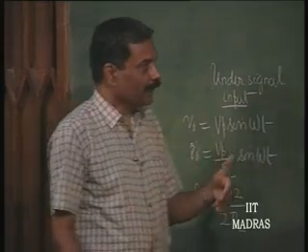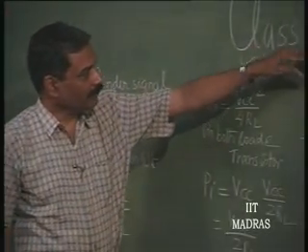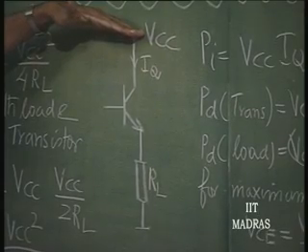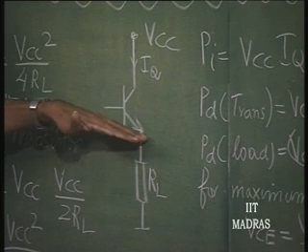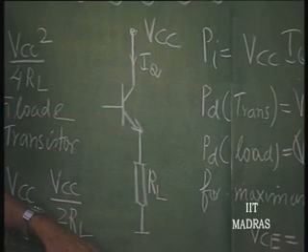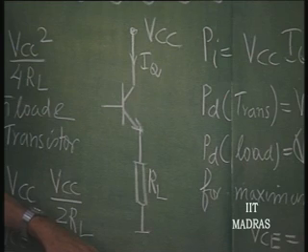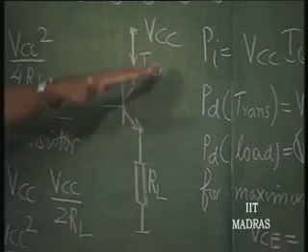So, if let us say we have the input power equal to 100 watts, initially 50 watts will be dissipated by this and 50 watts will be dissipated by this, and the maximum signal output power you can get when you have 100 watts is 25 watts.